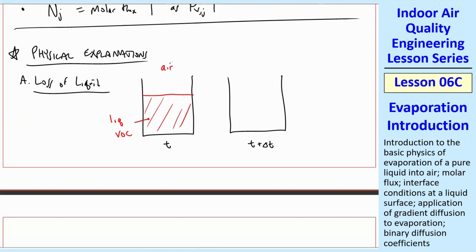What happens? Well, it's evaporating. The equations we give will be steady, but we call it quasi-steady because this is happening very slowly. So at any given time, we can use our equations. But if you wait a long time, you actually lose that liquid. Take a cup of water and stick it on a shelf and come back a week later, and it'll be a lot lower in level than it was because a lot of it evaporated.